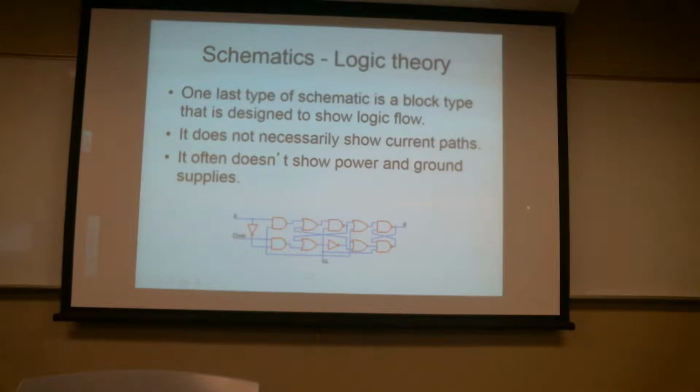The idea was they didn't want to make a whole bunch of switches, going this way and that. They also wanted to have something that if I went down one time, it would turn all the loads off, or take it back to just the lightest load. So inside there's 7 banks of resistors. They're actually big coils of wires that can absorb several hundred amps of current being put out by the generator.